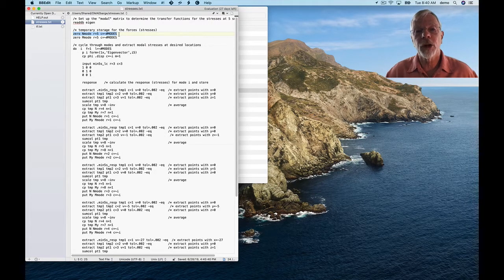Honestly, if I had it to do over again, I would only do the P over A component. In this model, because we've smeared the stiffnesses, the M C over I component really has questionable physical meaning. And the resolution of the model isn't going to give you high accuracy in terms of localized stresses. So it's fine for nominal stresses, the P over A kind of thing, but it's questionable for the extreme fiber stresses. But because I did it in the paper, I'm doing it here, and it adds quite a bit of complexity.